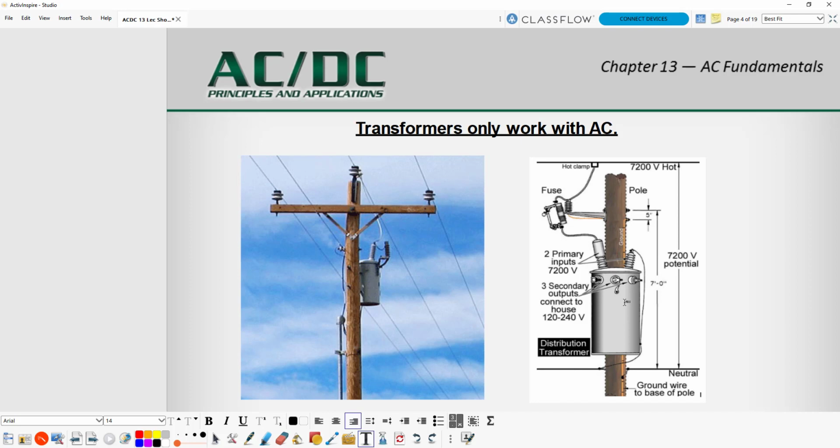So in our homes, coming out of every one of our residential plugs, receptacles, is 120 volts. Now there are some exceptions for the hot water heater, for our ovens, for a central heating unit. Certain devices in our homes do use 240, but this is not two phases, but two legs of 120.